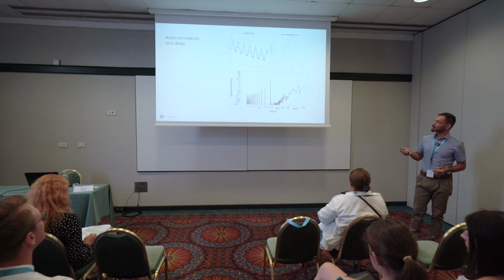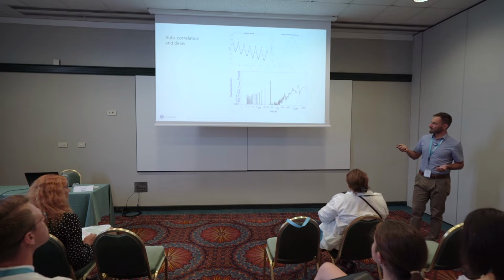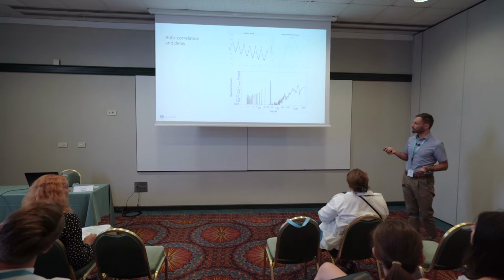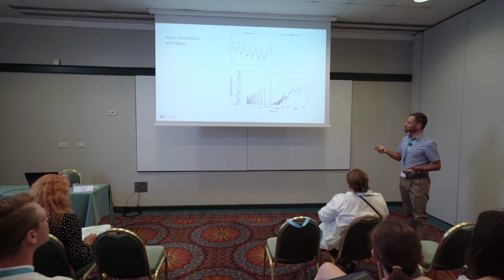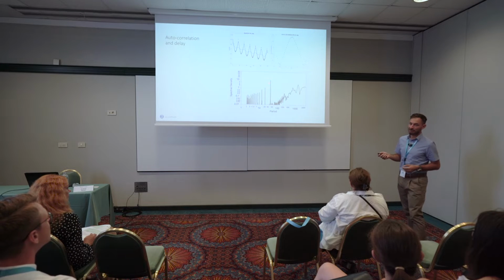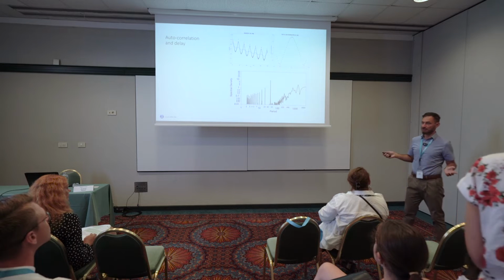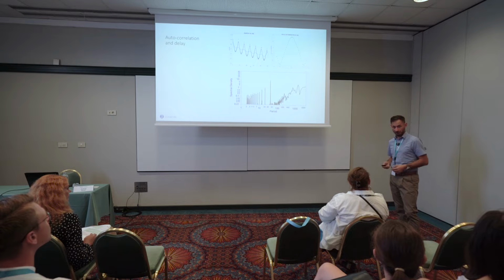We have checked the so-called autocorrelation. We did the periodicity analysis, which is fast Fourier transform of the data, and we saw at the 41 minute mark we have a very strong signal, and this is exactly this changing. So 40 minutes is one cycle: left burning, right burning, and then back to left burning. And this can be very nicely seen on the data. We have checked the autocorrelation and the stability of the process, and we saw that the process is stable. We can work with that.